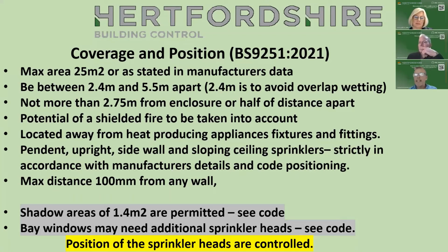So what they've said is that if the people in the block are vulnerable, then you go for an enhanced water and power supply. And to be fair, the fire authority tend to pin that. They tend to stick that on their reports. The second they see it's for vulnerable people, they'll automatically ask for enhanced water supply, enhanced power supply, so a secondary power supply, and often a supplementary supply from the outside that the fire brigade can tap into.